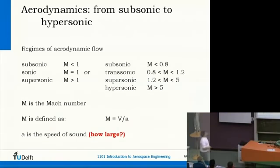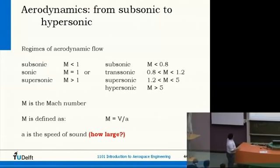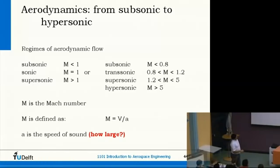Speed of sound. For the speed of sound, we often use the so-called Mach number. The Mach number is defined as the velocity, the true airspeed of the aircraft, divided by the speed of sound. If this number becomes 1, we are flying as fast as the speed of sound. And then we have a sonic flow. We are flying sonic. Beyond that, it's supersonic. Below that, it's subsonic.